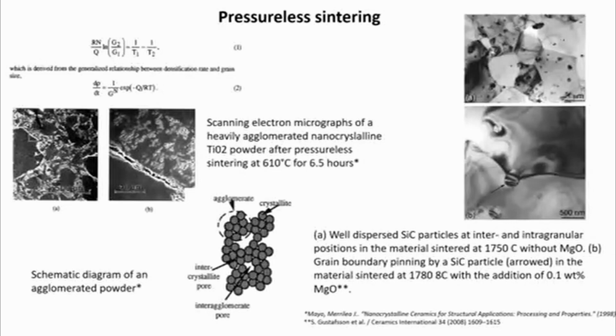The production of a fully dense material with a homogeneous dispersion of the reinforcement agent is a key factor in the fabrication of ceramic nanocomposites. A porous microstructure and agglomerated second-phase particles would degrade the performance of the composite material. It is well established that inclusion of second-phase particles may suppress grain growth, but the particles will also obstruct densification.